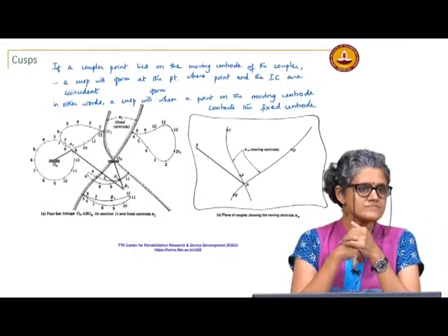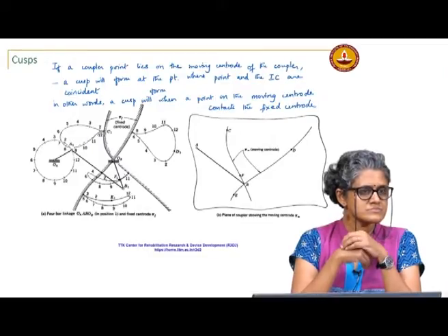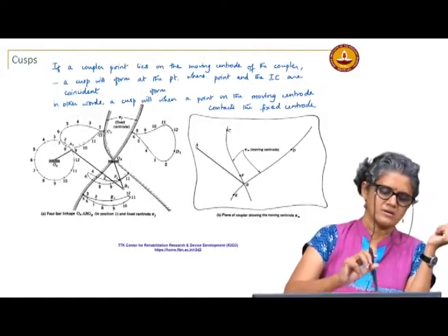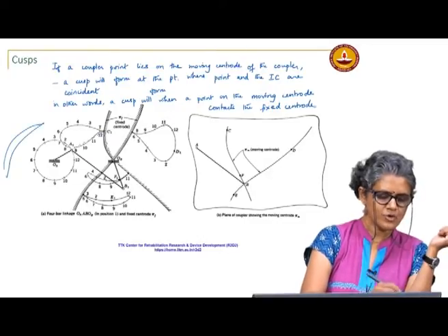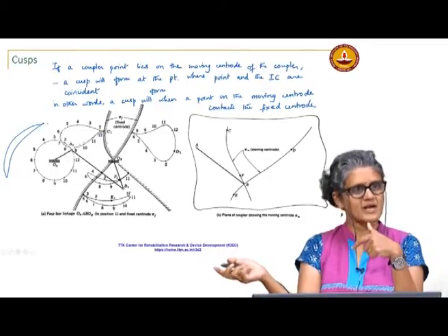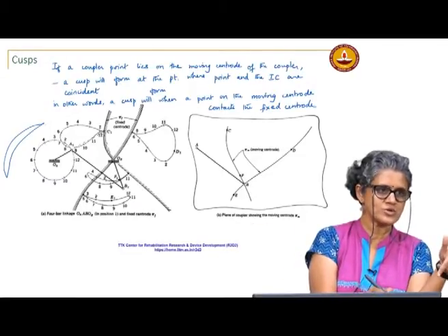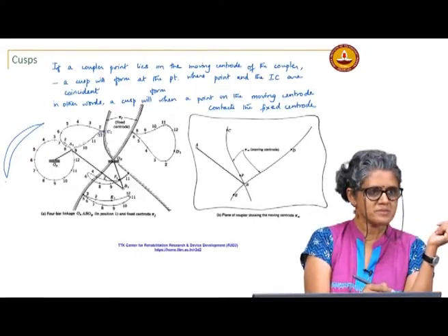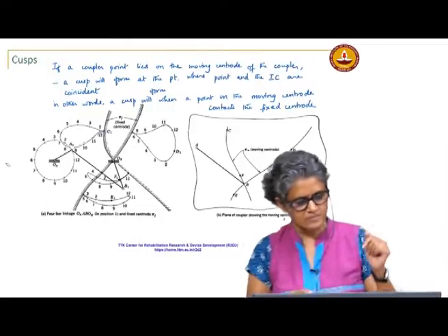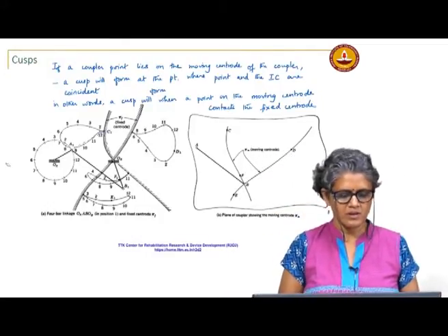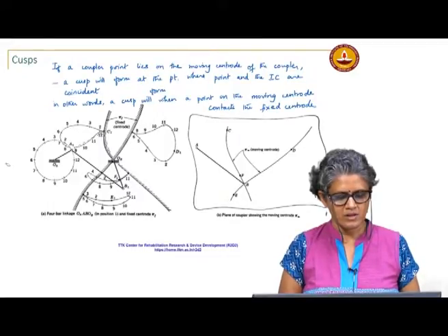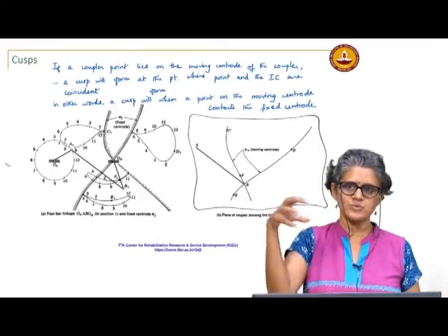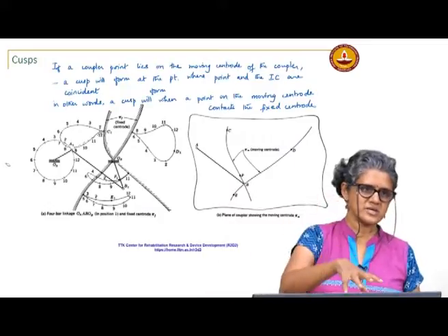There should be two cusps in the coupler curve for pick and place kind of. Yeah, it depends. So, for instance, you could have this kind of a curve, no? Or you could have some other point having a cusp. So, you could pick one place and drop it at some other place, for instance. Or it could just be a pick operation. So, something is there, it approaches it, picks it up, takes it.